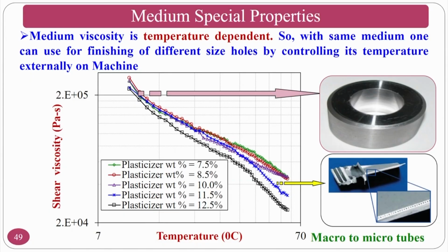Okay. So, using electromagnets and an external magnetic field. Here, for the abrasive flow finishing medium also, some of the reports say that you can control the viscosity, you can control the rheological property using the temperature. These polymers that we normally use in the abrasive flow finishing medium are temperature sensitive,